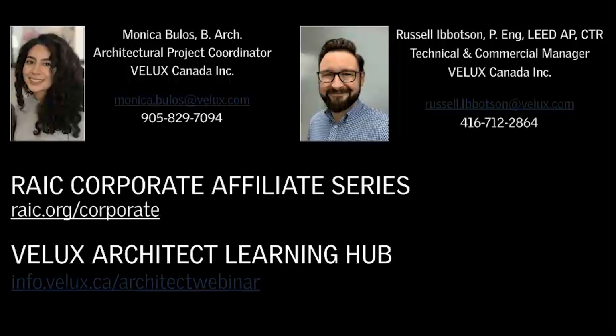So there's a question about blinds on the exterior rather than the interior. With regards to light control, if you're just looking at glare, then the exterior and interior blinds are going to have a very similar effect. If you're working with blinds for the purpose of reducing solar heat gain, then with exterior blinds, when the sun hits the blind, it's heating the blind up, but it's still on the outside of the glass. So not as much heat with an exterior blind is entering into the building.